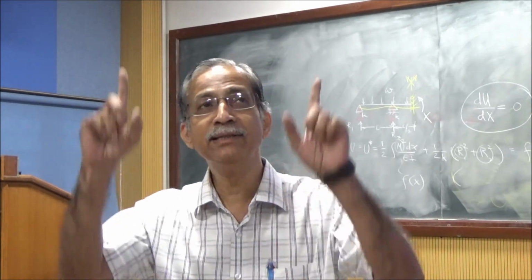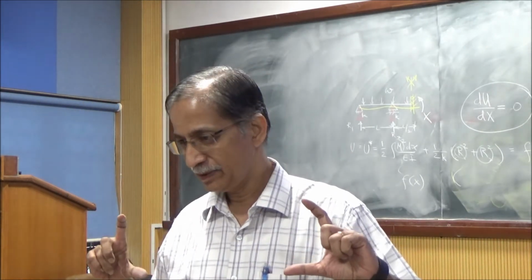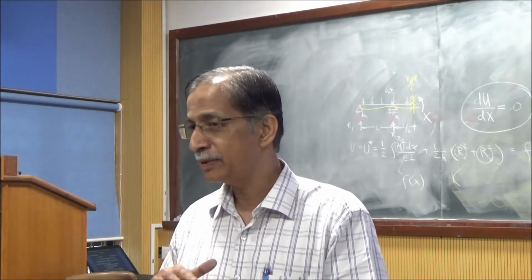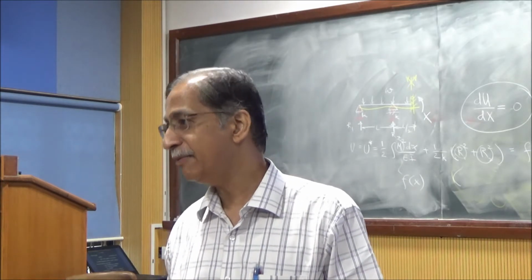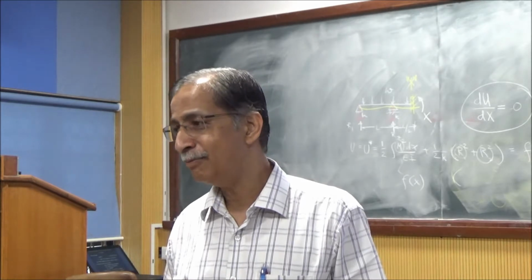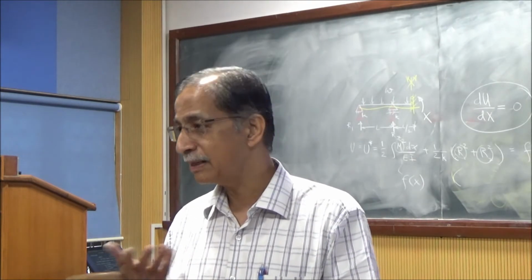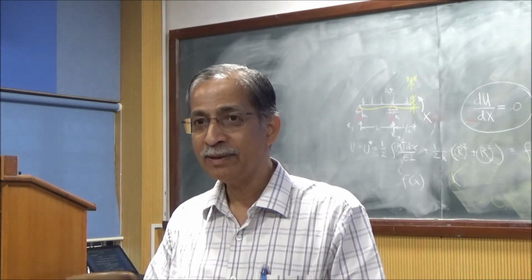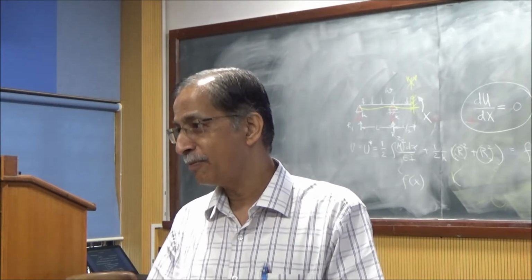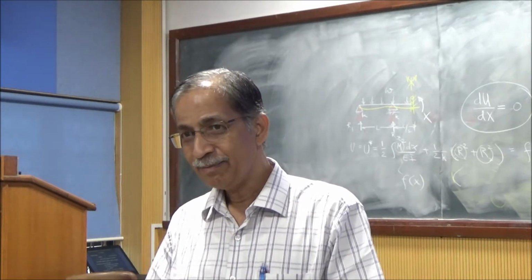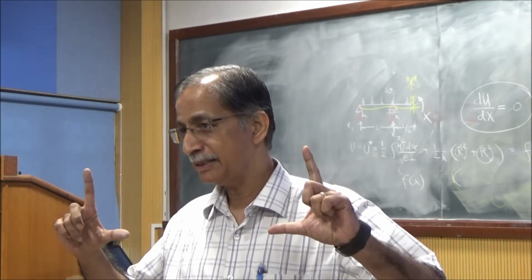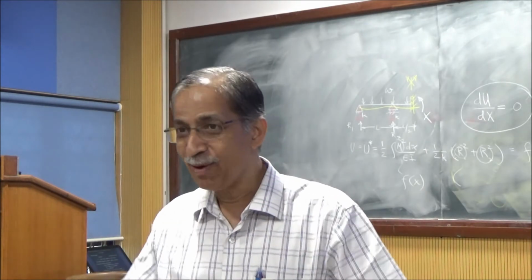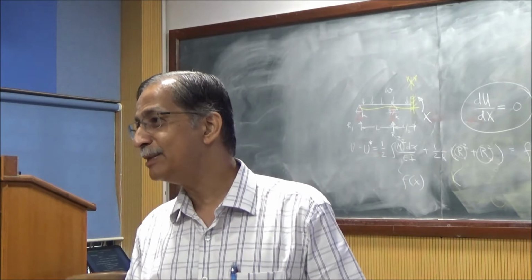In a normal slab like this one, the slabs are relatively thin. But when you don't have beams, the slabs are thick. 1 foot thick, 300 mm, 350 mm. They're very heavy. And the dead load of the slab is much more than the live load that will come later on the slab. So when you're casting a slab on one floor, normally you prop up from the floor below, right? But the green concrete of this slab that you're casting is going to add a load onto the slab below, which is more than the live load that slab has been designed for.